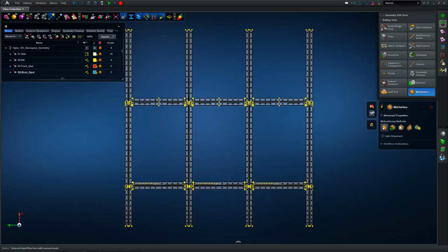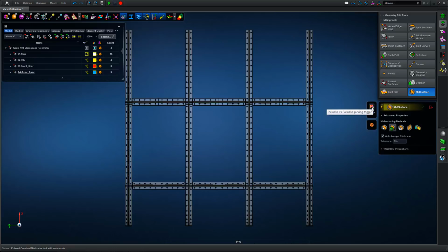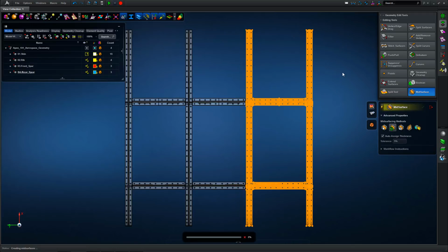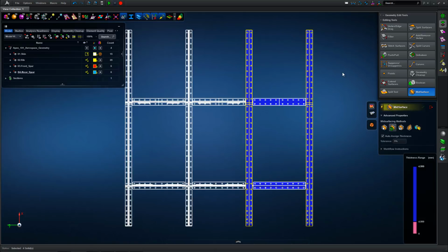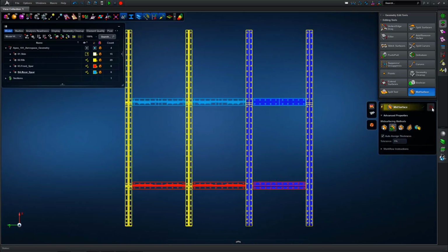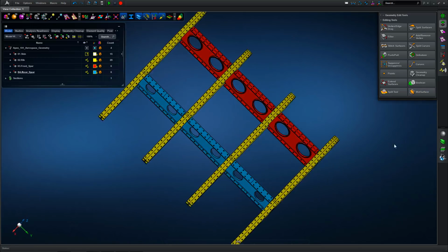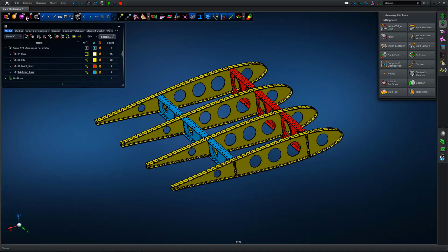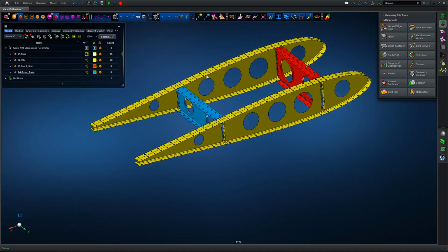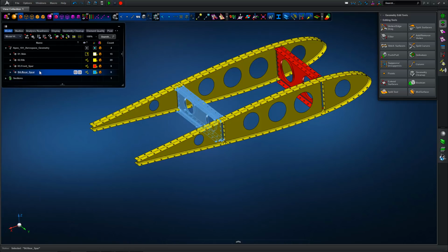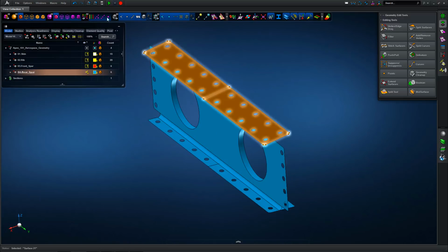So this is looking at a 2D shell meshed idealization from a rib to rib, so a single bay definition. So we're looking at mid-surfacing with auto assign thickness turned on, such that the mid surfaces are generated and the three-dimensional CAD data that was used to create those mid surfaces is stored as a thickness explicitly to allow us to define properties onto the FEA entities later on.